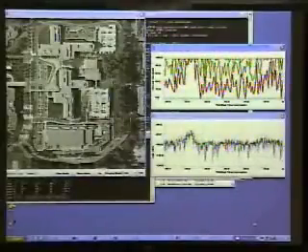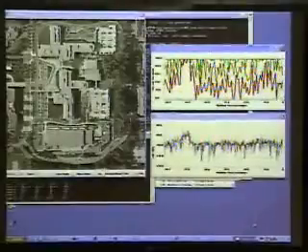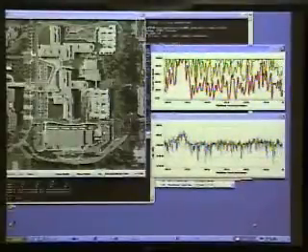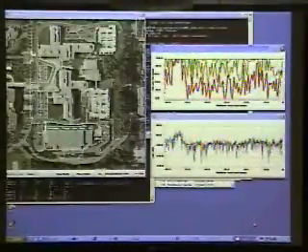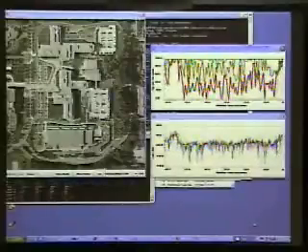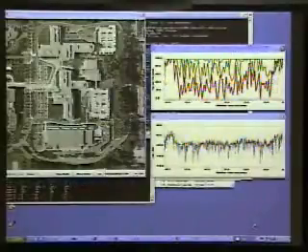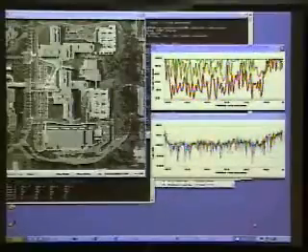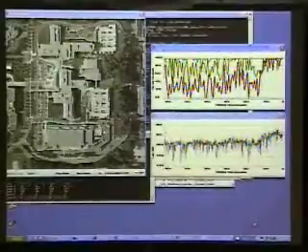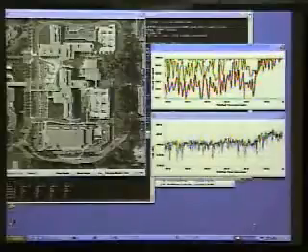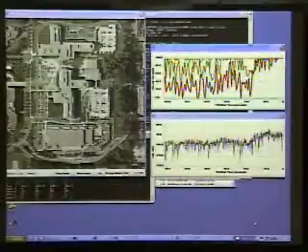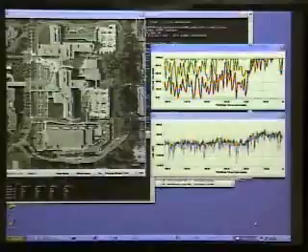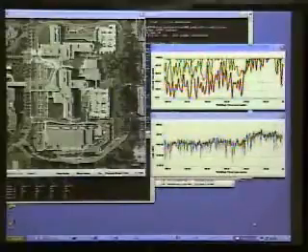So this is 802.11b. That's right. This is all 802.11b. Can you support G at high data rates at 54? Sure, we can. Yeah. So the answer is yes. The biggest question for us is the frequency band, and G is in the same band, so sure. For A, we would need to make a new RF front end. You swap out that RF front end, and we can do it. Although A has such a large bandwidth, we might need to change something to get that whole bandwidth.